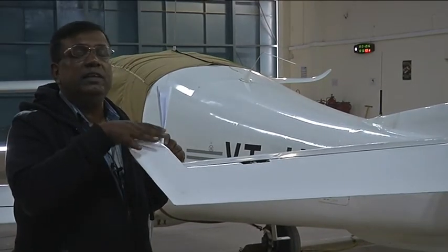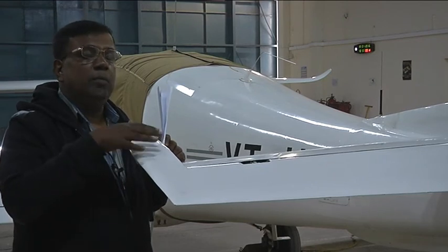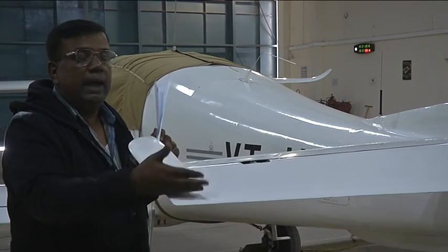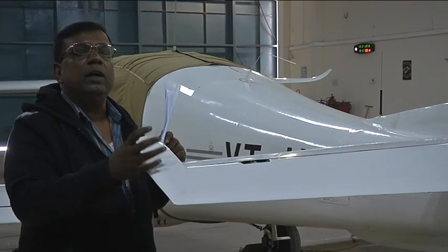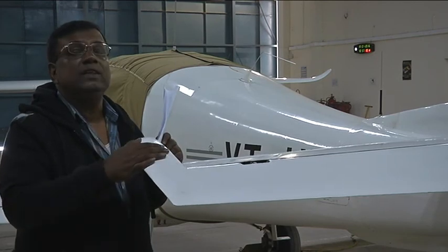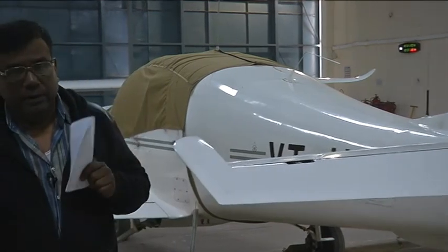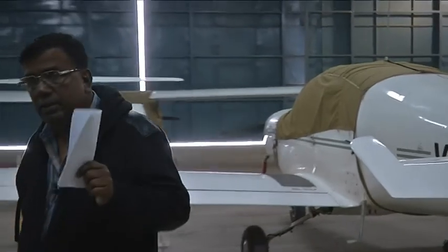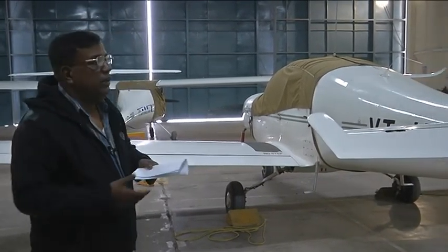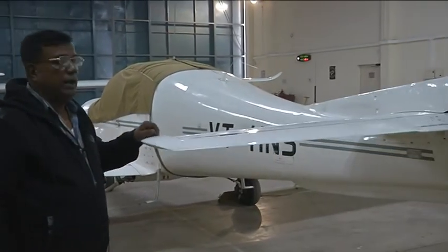This surface ahead of the leading edge will give a moment opposite to the moment generated by the surface behind the leading edge. So, if you want CH alpha t to be 0, ensure that they cancel each other and CH alpha t becomes 0. Okay? This is how we reduce the value of CH alpha t, or that is how we reduce the floating tendency of an elevator through Horn balance.